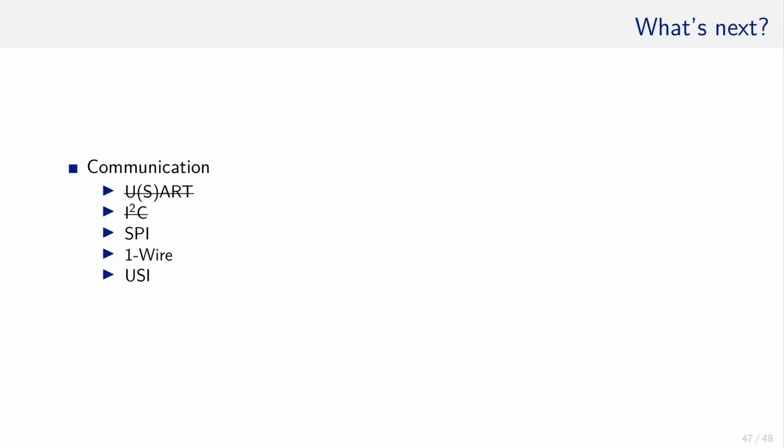So what is next? So far, we introduced the UART and the I2C protocol. The next protocol in the list is the SPI protocol, which also has a hardware unit integrated into the ATmega 328P. Although SPI is not that often used compared to I2C, it is required especially if SD cards are to be accessed, as their protocol is SPI.